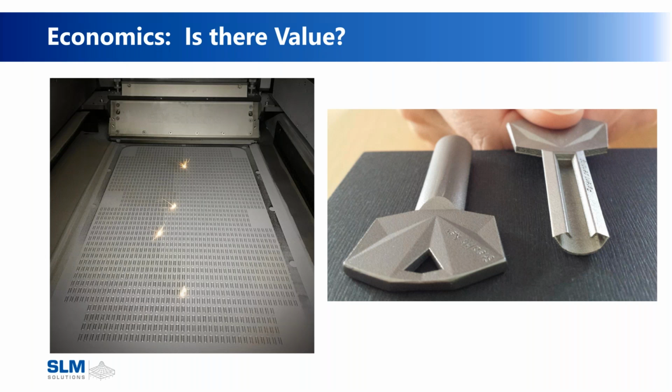And on a SLM500, we were able to build over 1,100 of these parts every single run. So that ends up making a lot of sense when you can pack the plate completely edge to edge. You can see there that that plate is completely packed front to back and edge to edge, excluding areas for the bolt hole clearances, which we talked about earlier. So every single run, building 1,100 makes a lot of sense. This wouldn't make sense if we could only build 400 or 500 parts per plate. It makes sense when we can actually pack the plate down and fit as many as possible.